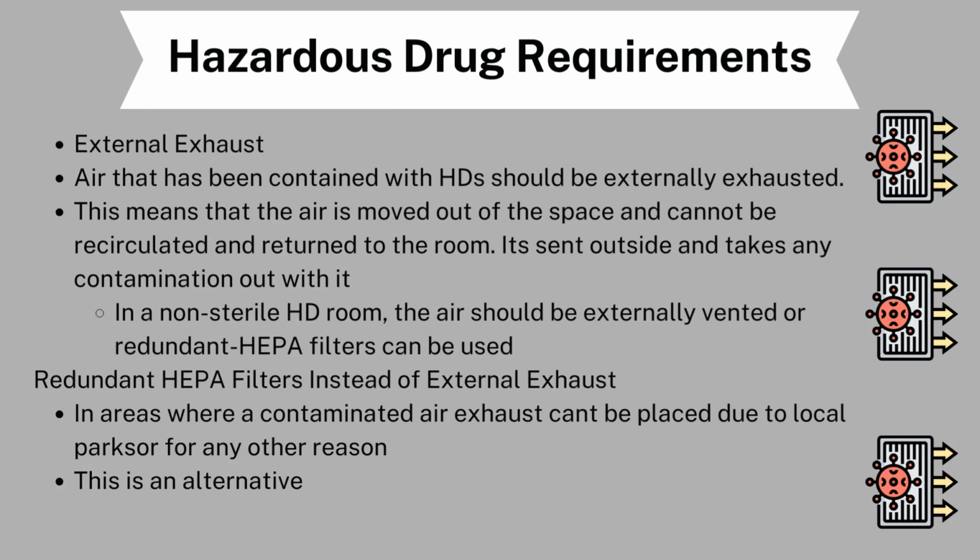When handling these hazardous drugs, the pharmacy needs an external exhaust. Air that has been in contact with the hazardous drugs should be externally exhausted, meaning the air should go out of the pharmacy. Like we just said, the air is moved out of the space and cannot be recirculated and returned to the room. It's sent outside and takes any contamination out with it. In a non-sterile hazardous room, the air should be externally ventilated, or a redundant HEPA filter could also be used.